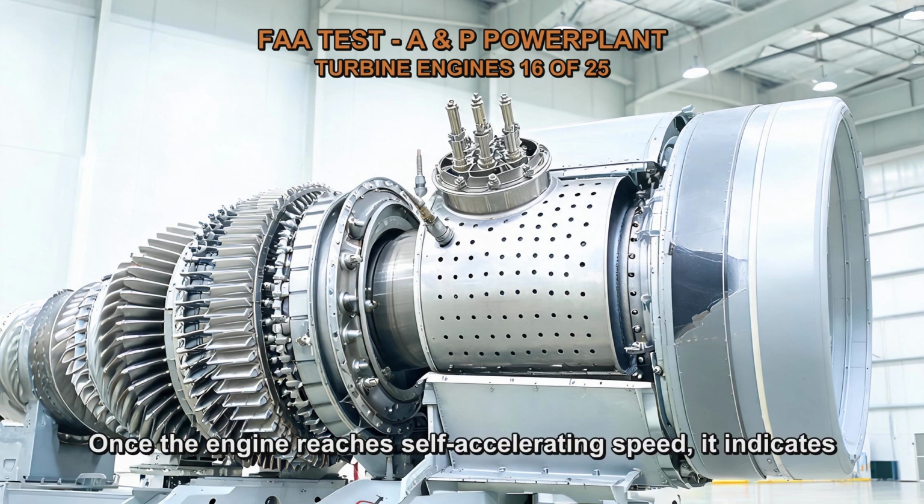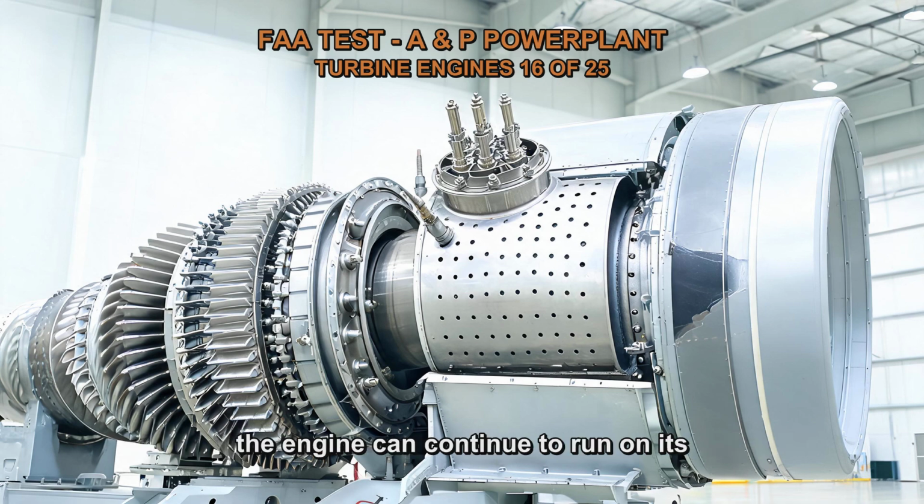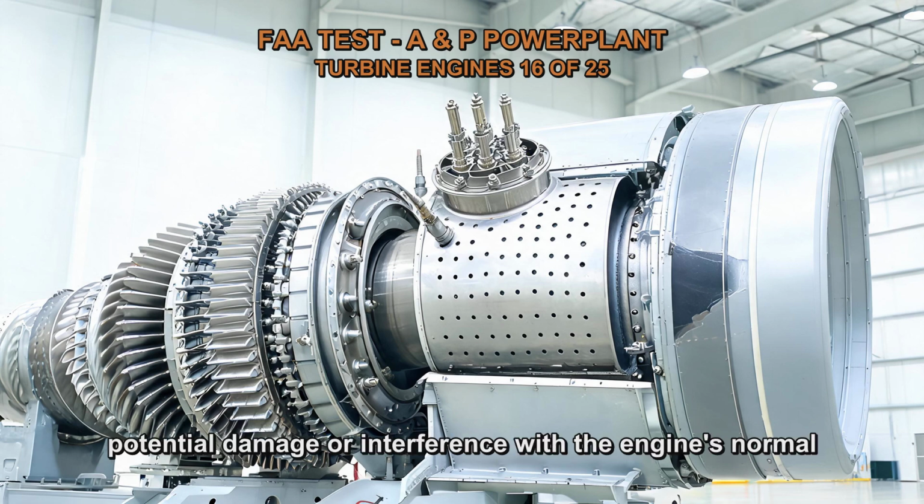Once the engine reaches self-accelerating speed, it indicates that the combustion process is functioning properly, and the engine can continue to run on its own. At this point, the starter is no longer needed and should be disengaged to avoid any potential damage or interference with the engine's normal operation.